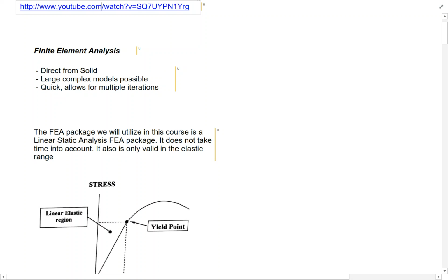So you say then, well, why do we do solid modeling, even if it takes longer? The reason you do solid modeling, even if it takes longer, is that I've got the capability to do things with that model, right? I can take that model and I can post-process it into a CNC program, so I don't have to sit there and write a G-code program. And the other huge thing I can do is I can analyze it. I can do finite element analysis on it to determine my stress levels and my strain levels. And I can also do other analysis on it.